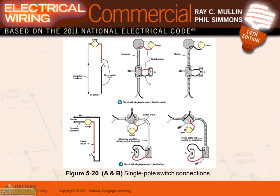So as you know, if it's in a conduit, it has to be color coded. If it's a cable, then you can re-identify the neutral. I want to bring to your attention, if you're wiring with cables, what do you need to do now? You have to bring a neutral. So you might have to kiss goodbye re-identifying the neutral as a hot, bringing hot to the system.